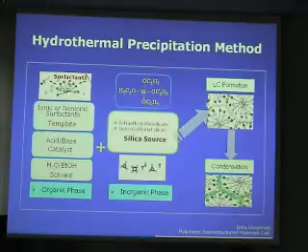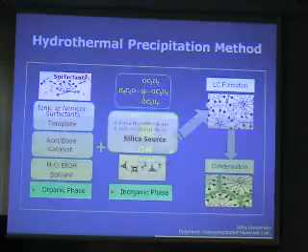They form the organic and inorganic self-assembly with a lyotropic liquid crystal-like order. This self-assembly is then heat treated to be polycondensed to form the inorganic continuous interconnected framework. Actually, the final product from this method is always in the form of powder.